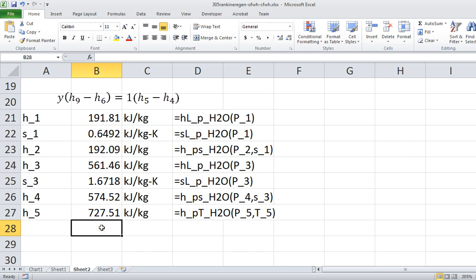Now, it's an interesting question, and you should be aware, if you're working this by hand, how would you find that property if the compressed liquid table does not contain an entry for 12,500 kPa? I think it actually does, the table in your textbook, so I think you could look this up. But the standard approximation for compressed liquid is that the enthalpy is a strong function of the temperature, and so we would look up the corresponding temperature of the saturated liquid.